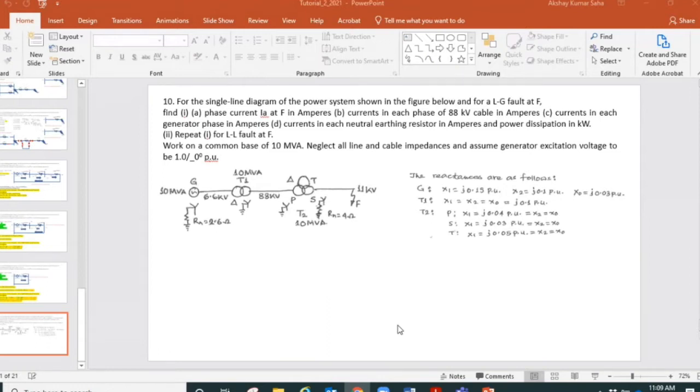And then we divide those harmonics into two categories, the odd harmonics and even harmonics. The multiples that we are taking, 2, 3, 4, 5, 6, 7, 9, 11, 10, 12, whatever, can be categorized as even or odd. So 150 Hz is an odd harmonic. Third harmonic is 150, 450 is the ninth harmonic, an odd harmonic, and things like that.